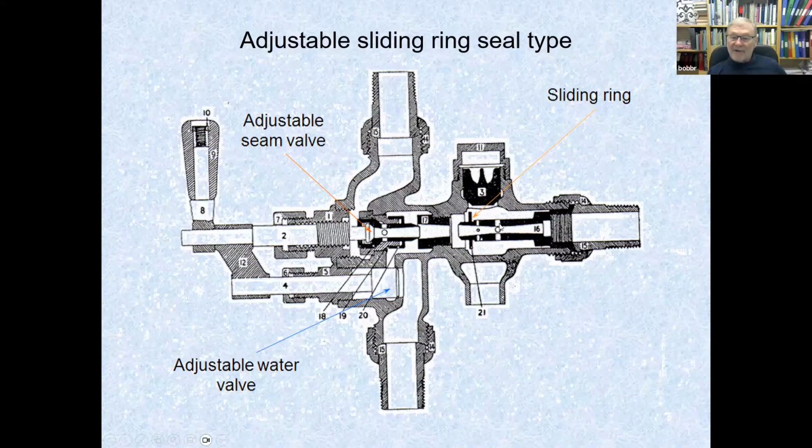And it goes through all these holes here, and it eventually goes through the delivery cone into the boiler. And there's this check valve here that stops the air coming through this. It's an annular space between here and there, so that communicates with that. When it's starting up, the steam and water bumps up that check valve and comes out here. Once it's going, there's a big vacuum in here, pulls the valve down and stops the air getting into the boiler. That's one type.